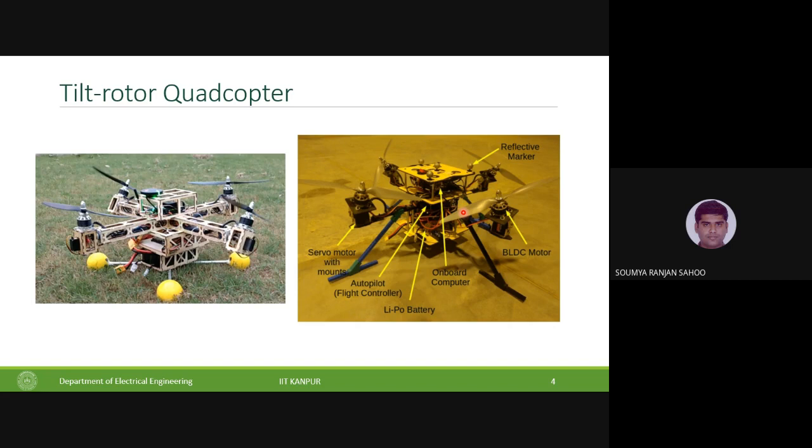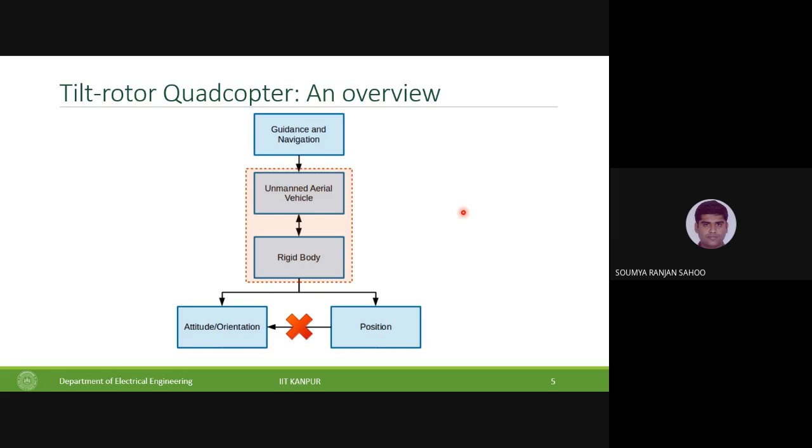Okay, so now with this design, you remove this coupling here. The position does not command the attitude anymore, so you can control the position irrespective of what the attitude is. So you can have an opposite roll while going in one particular direction, which is not possible in conventional quads or any other quad that doesn't have this design. So this is the flexibility that you have now achieved. Of course, the cost of this was increasing the number of actuators in your system.